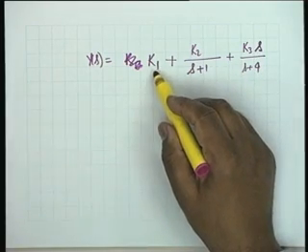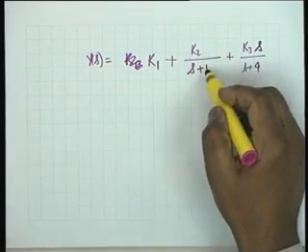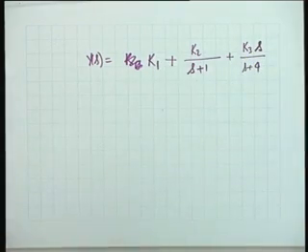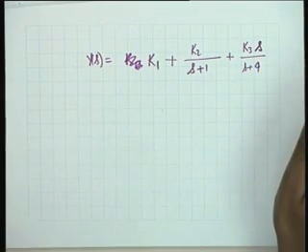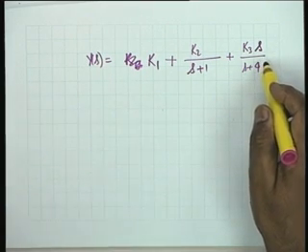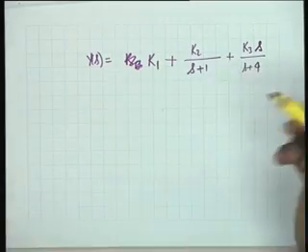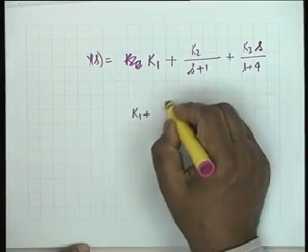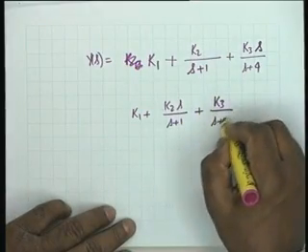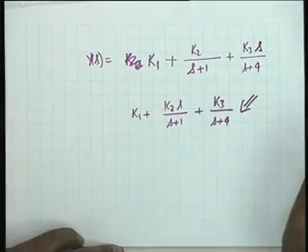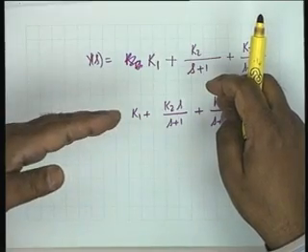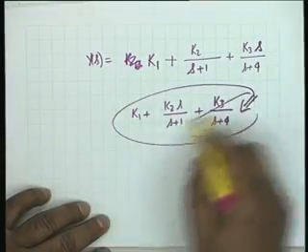This will be a parallel combination of resistance and capacitance, and this will be a parallel combination of resistance and inductance. Now, nobody told me beforehand whether K3 will be positive or not, and there is nothing sacred about assigning the pole at s equal to minus 4 to K3 s by s plus 4. I could have done it the other way around. For example, I could have written K1 plus K2 s by s plus 1 plus K3 by s plus 4. Why don't I do this? Because K3 is found by the same procedure, and K3 was found to be negative, so we don't try this.